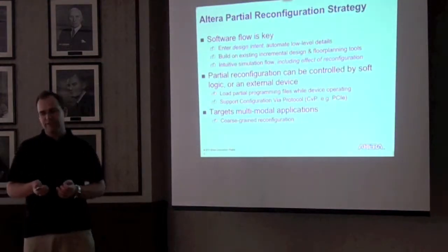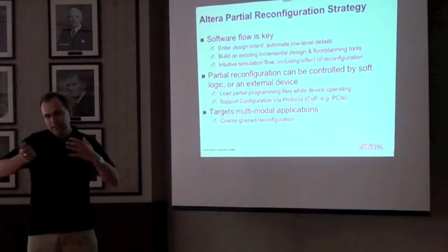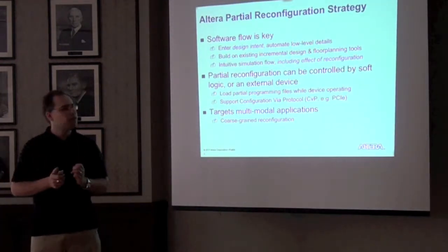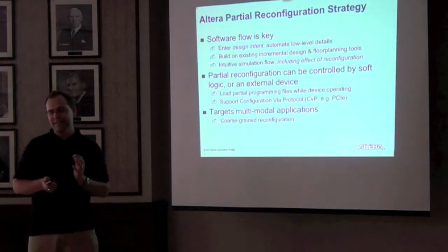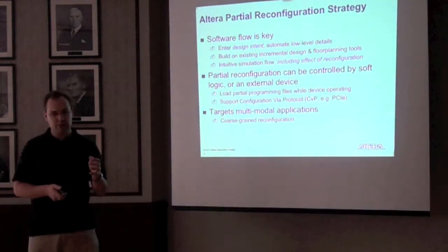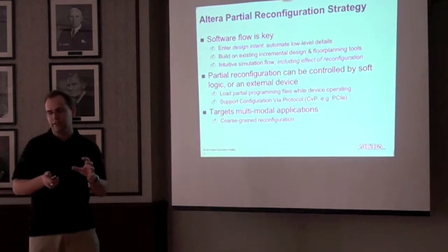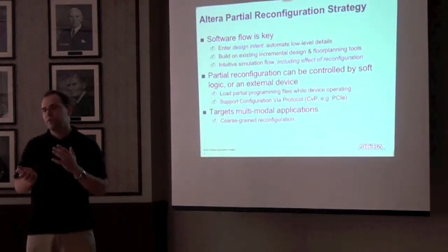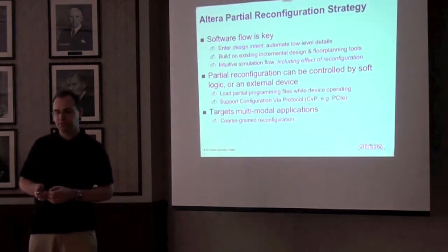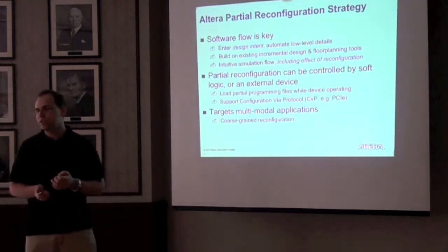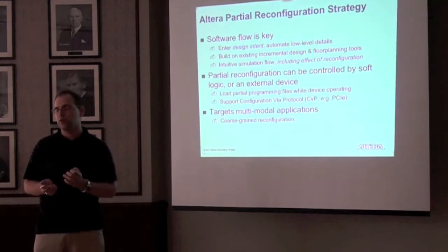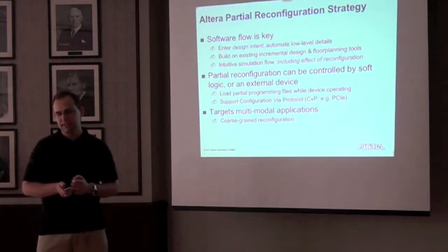So Altera's partial reconfig strategy is to really focus on the software flow. We want people to enter the design intent, basically saying, I have a bunch of modules, this one is reconfigurable, and here are the different instances, and then let Quartus automate all the low-level details. We want to leverage our existing incremental design infrastructure, I'll go into more detail of that later, and our floor planning tools to make this process as easy as possible.